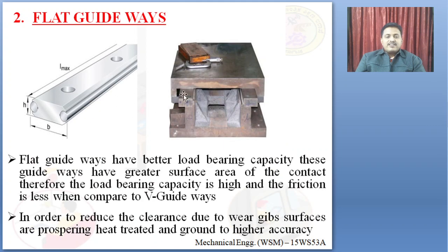Next is flat guideways. Flat guideways have better load carrying capacity than V guideways, because they have a greater surface area of contact and the load bearing capacity is very high. Friction is very low compared to V guideways. I think this is a very good guideway. Flat guideways are used in industries today.